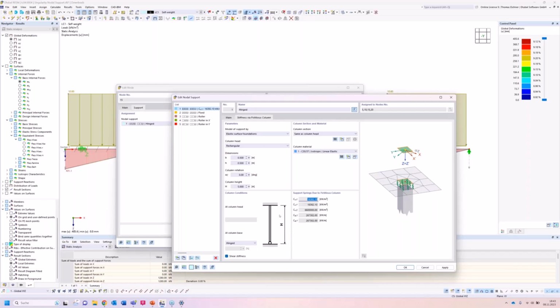And the program helps a lot with this. We can just enter our estimated story height. In general, we know it. This is 3 meters right now. We can say the dimensions of the column, 0.5 times 0.5 meters. It's again a really big column. I think the biggest one I saw was 0.4 times 0.4. But also we have not so many like skyscrapers, so that's mainly the reason why I didn't have to plan much more.